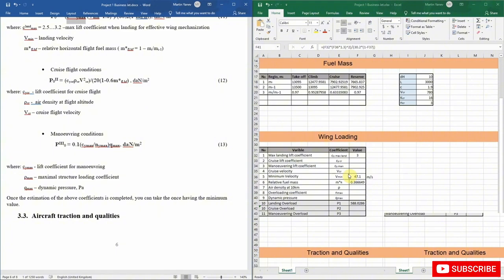If the lift is too high, the aircraft will be climbing, but this is not what we want in cruise flight. So normally at cruise level the lift coefficient will be about 0.53. For example, for the A320 it's about 0.566. So between 0.5 and 0.6 is a normal lift coefficient during horizontal flight.